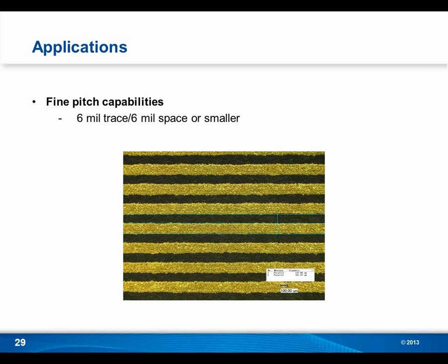Yeah, so definitely, if you want to run a lot of current on an LDS part, you would probably have to create wider traces for this. And we have some graphs and schematics and calculations for this where we can help you with that. So if you want to run a lot of current on a part that has fairly thin plating, really the only way to do this is to make the lines a little wider. However, the good thing is we use a lot of real estate here on plastic parts that usually hasn't done anything in the past. So in many cases, there is the real estate available to make those lines a little wider. This is typically common if we see LED lighting applications or other lighting applications, because those need a little bit more current than we see with common RF antenna applications.